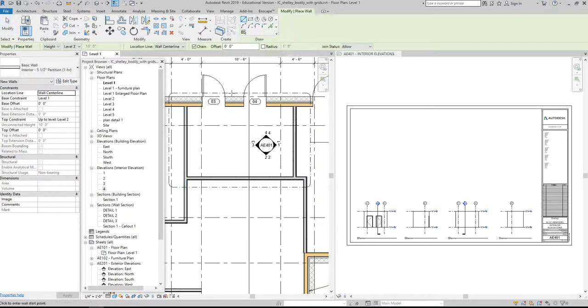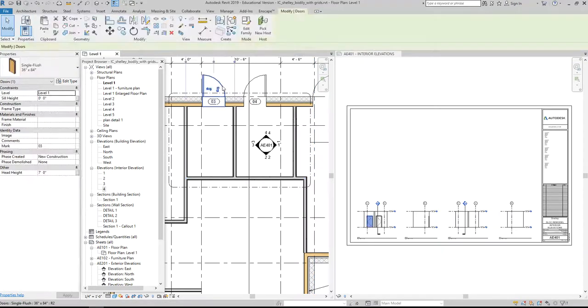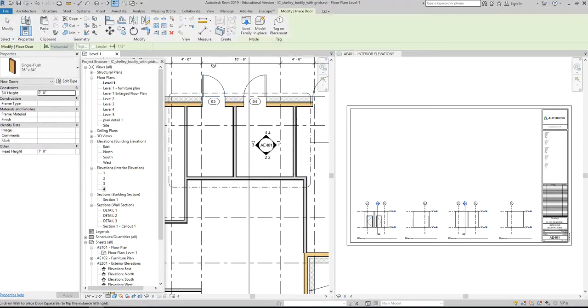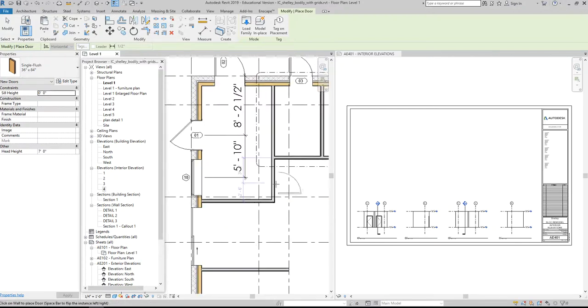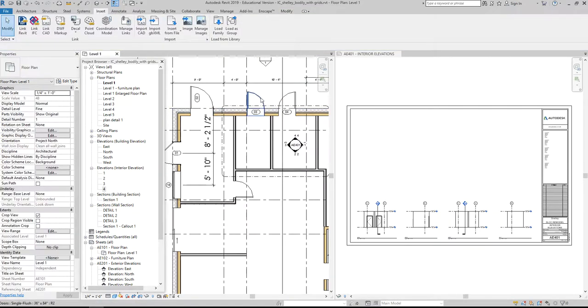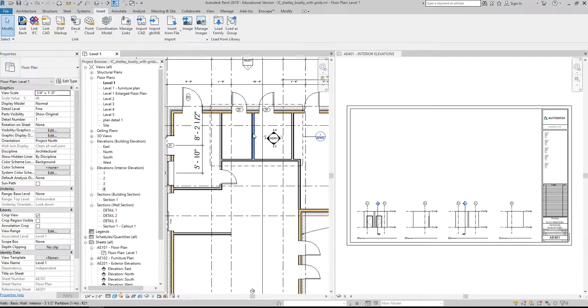Create similar will allow me to begin placing that identical element regardless of what it is. So it can be a toilet, a wall, it can be a door or a window, but I can click on like door and choose create similar. How much faster is that than going to door, searching through a gigantic menu of doors, finding the door you want and then placing it, right? Even though you know you want to use this door, okay?